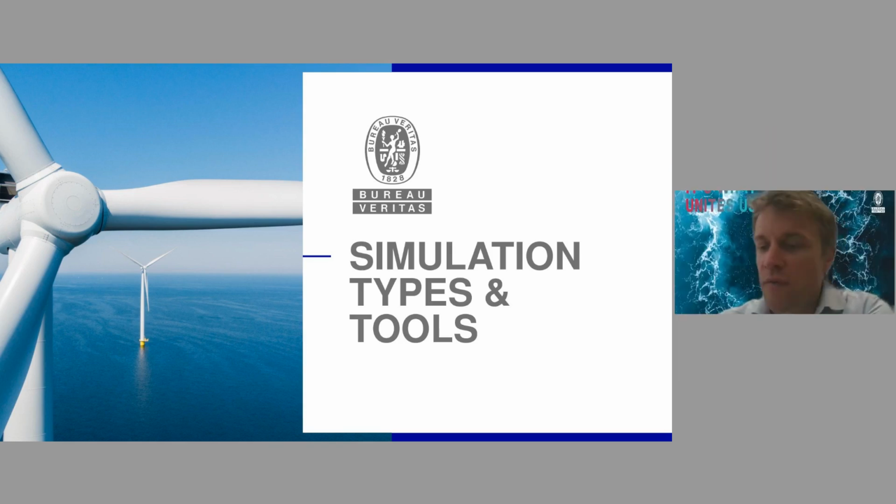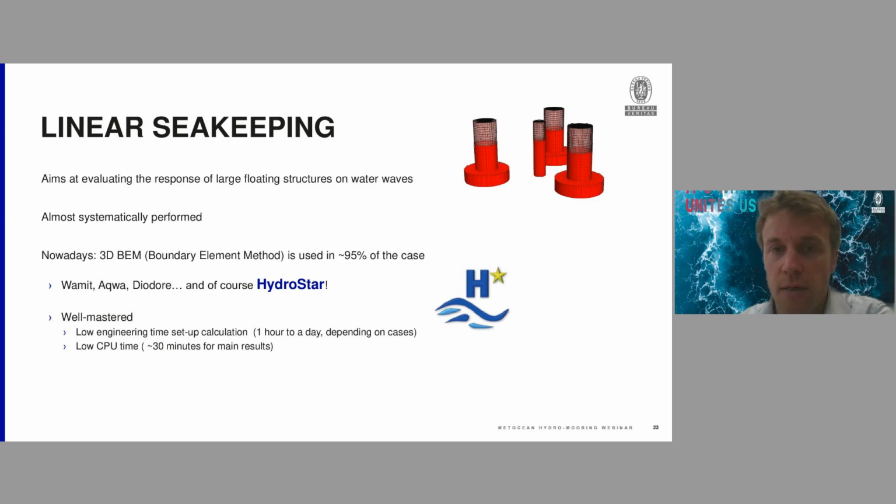So now that we know in which environment we should simulate the behavior of the units, I will go into the detail about the simulations that we can do. I will start with the basic and generally the first step when you assess a floating structure, which is so-called linear seakeeping. It aims at evaluating the response of large floating structures to water waves. It's almost systematically performed because nowadays there are a lot of commercial tools available and it's well mastered. Examples of such software are WAMIT, Aqua, Diodore, and of course Hydrostar, which is developed in Bureau Veritas.